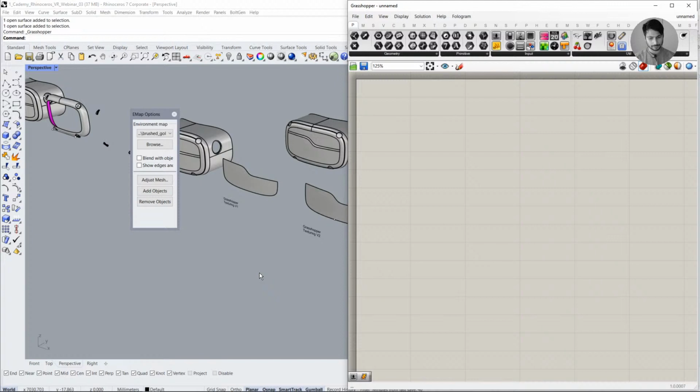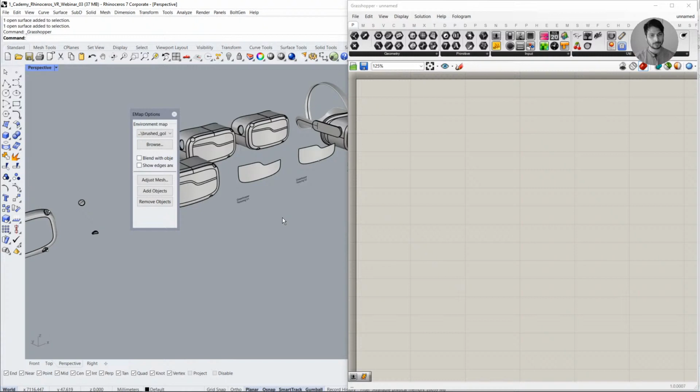Why didn't you rebuild the curve first but rebuild the surface after the creation? If you just rebuild the curve, it's just going to create a surface that is trimmed, in a planar geometry. So it's not going to have these additional internal subdivisions. It's just going to create a simple, probably 2 by 2, degree 1 surface on UV, but with the trimmed part. So the parameter curve is not defining the internal UV parameters of the surface, and that is why we had to add those additional control points.